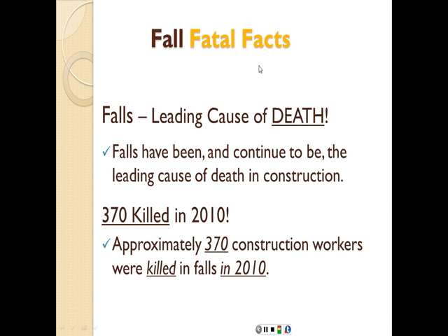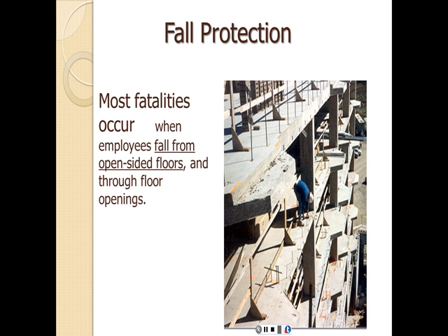Some fatal facts about falls. Falls are the leading cause of death. Falls have been and continue to be the leading cause of death in construction. In 2010, for example, based on statistics from the Bureau of Labor Statistics, we had 370 people killed on construction sites resulting from falls. Most fatalities occur when employees fall from open-sided floors and through floor openings.